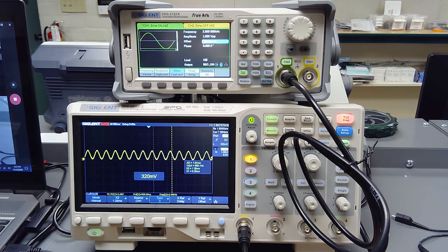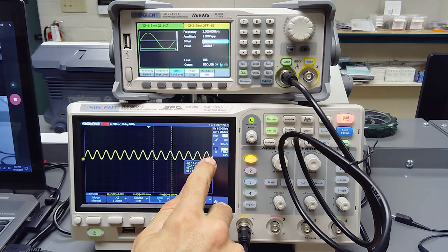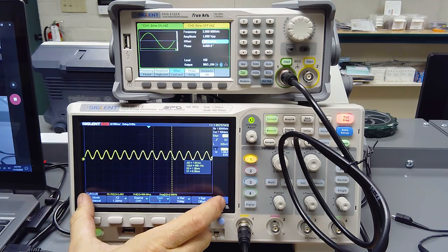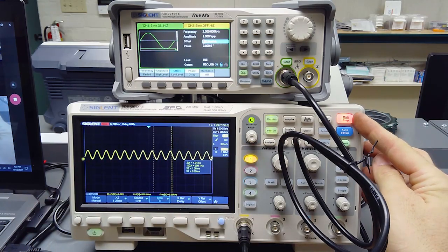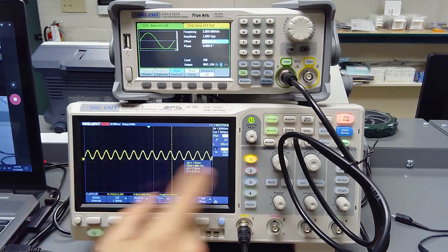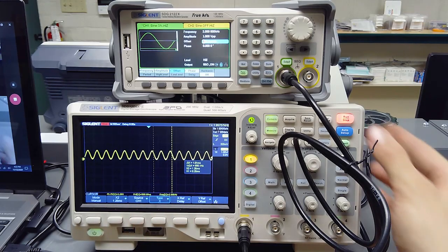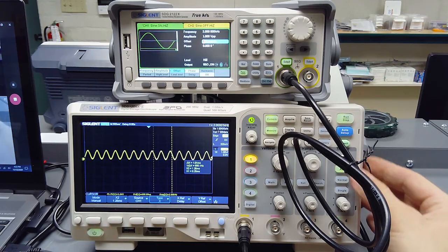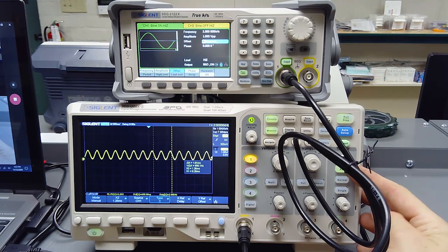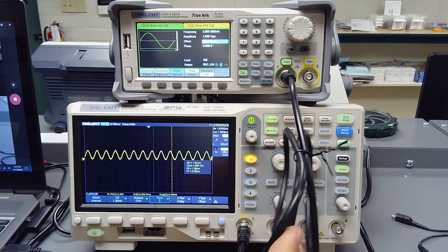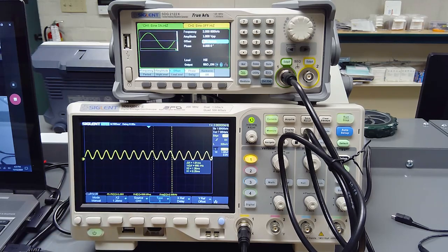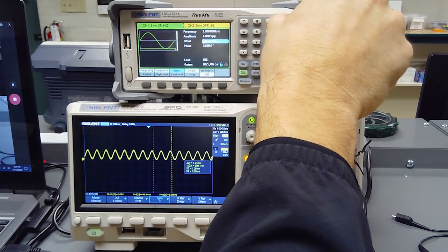Okay, now it triggers at something above 0 volts where this triangle is, and it captures the waveform. So that's 1 screen's worth. If you look up here, it says stop. It's red now, so that means it's not capturing. It just captured 1 screen's worth and it stopped. If I hit run again, it'll capture continuously now. And this changed to auto instead of single. Let me move this so you can see it. So this is in auto mode. Now this is continuously capturing the waveform. So if I change it, you'll see it change.